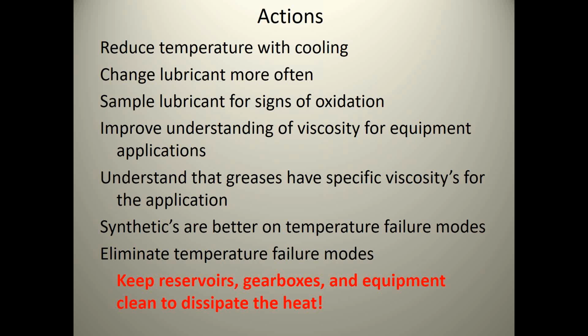Improve your understanding of viscosity for all your equipment. As the temperature goes up, we have to understand what the equipment temperatures are. A lot of times, I tell people, an OEM will recommend a specific viscosity for their equipment, whether it's a hydraulic unit or a gearbox, but sometimes the OEM does not know where you're going to install that equipment. So he may not understand they need to change that viscosity.